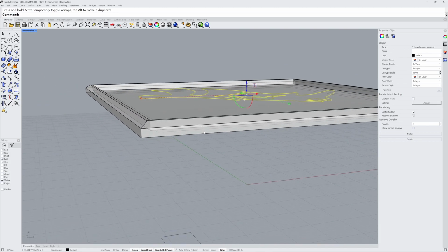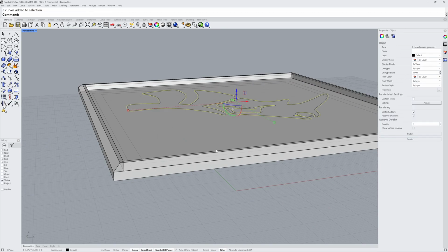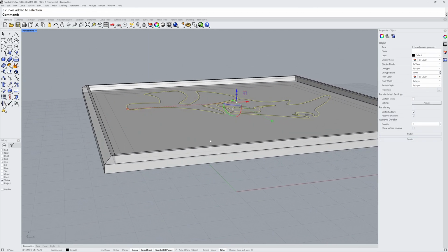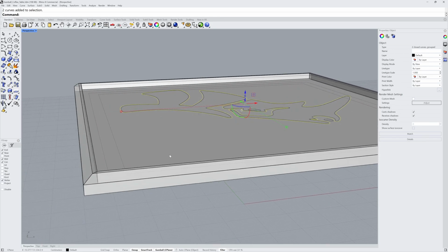From this location, we can extrude down with that outer logo curve and create a boss. This will be an extrusion attached to that object. If we mouse over the cut handle on the gumball, which is that horizontal line, we can click and drag and use the Control key to create a boss. A boss will be an extrusion that is connected to the object it intersects.